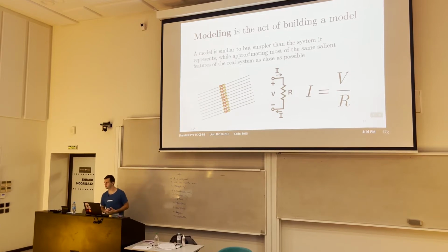But sometimes it's tricky when we talk about complex systems. For example, you want to model the interaction of a robot with the environment. Do you need to describe the interaction of each point of this robot, or maybe only of the end effector? That depends on your task. If you create a model of the entire structure with the environment, it will make your system much more complex, and it will be harder to simulate on the computer.